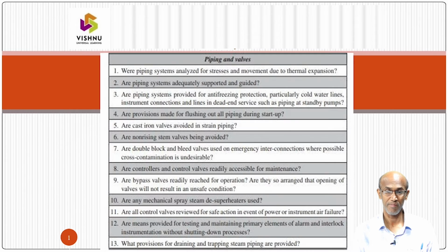of operations? Piping and valves: were piping systems analyzed for stresses and movement due to thermal expansion? Are piping systems adequately supported and guided? Are piping systems provided with anti-freezing protection, particularly cold water lines, instrument connections, and lines in dead-end service, such as piping at standby pumps? Are provisions made for flushing out all piping during the startup?